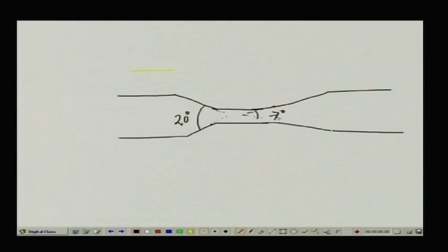One is for the larger downstream portion, okay. Another is the smaller downstream portion. You will find that if you make this angle even lower, your pressure recovery will also be higher. But it takes a large space and all those things, that is the restriction of the venturi. In fact, the pressure recovery in the shorter venturi is less. That means, the permanent pressure loss will be more in the case of the short venturi than the longer standard venturi.